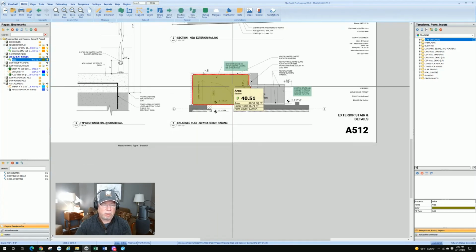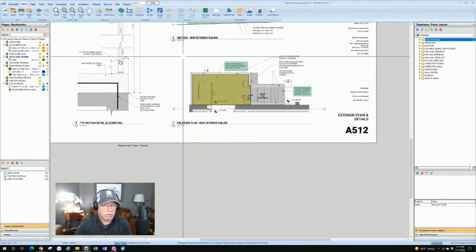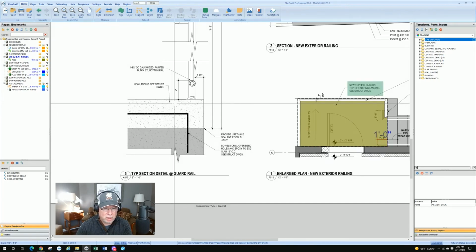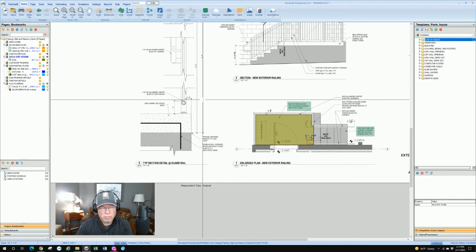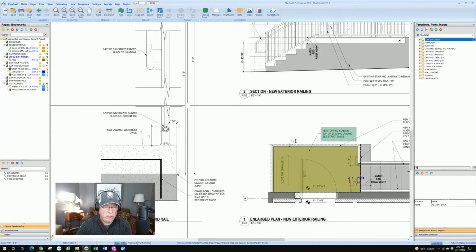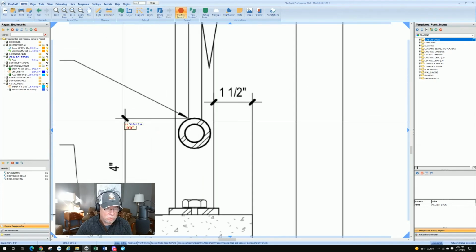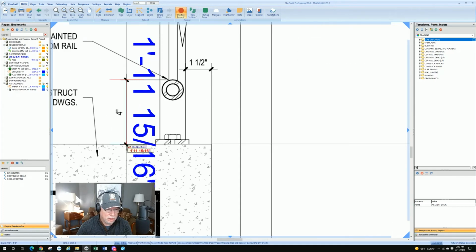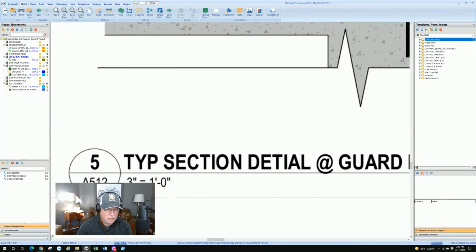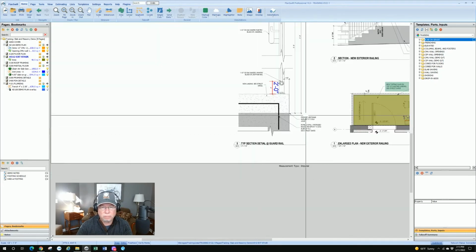Now I'm depending on knowing that area for my takeoff. But here I've got something where I don't need to do a takeoff, but I need to check something. I'm going to go ahead and use my dimension. The first thing I do is check the scale. I'm going like, well, that's not 2 feet. Why is that? Because it says it's a different scale.